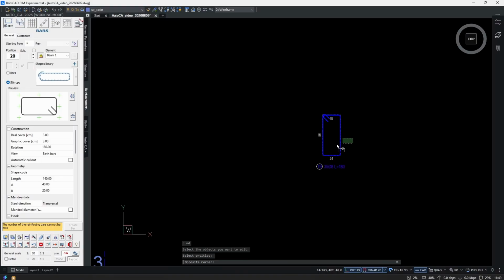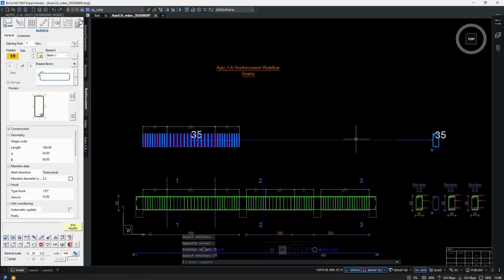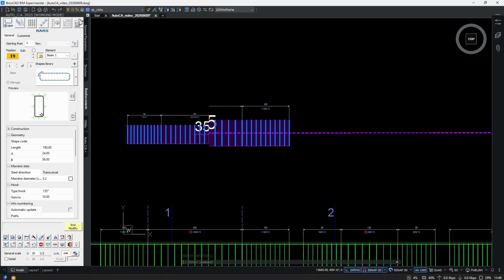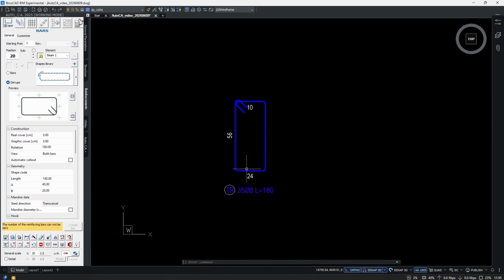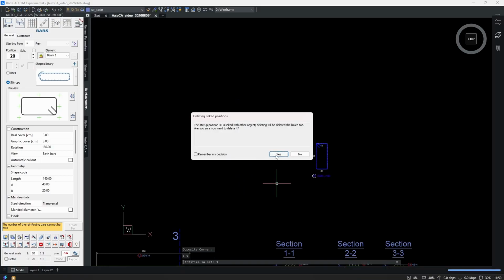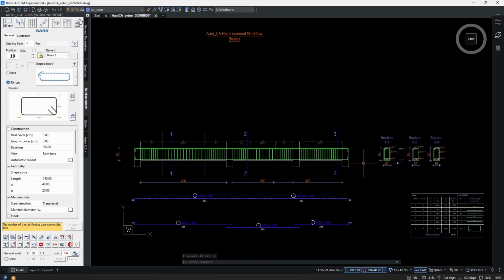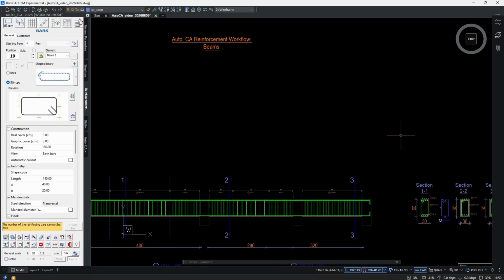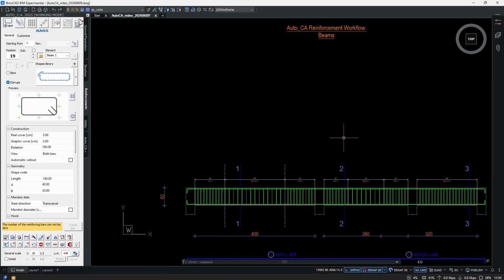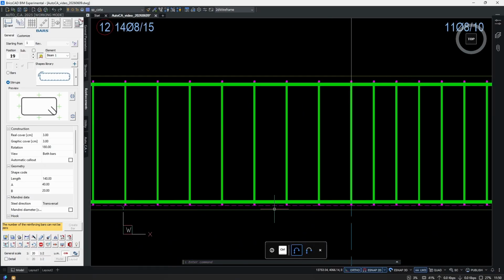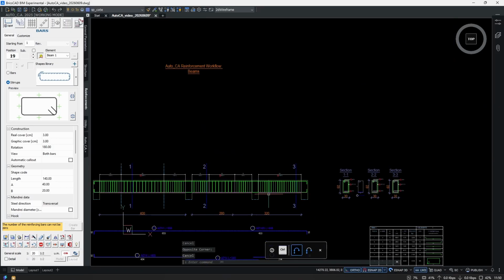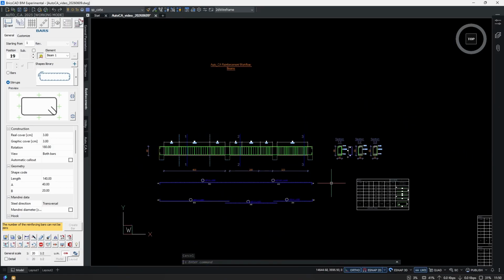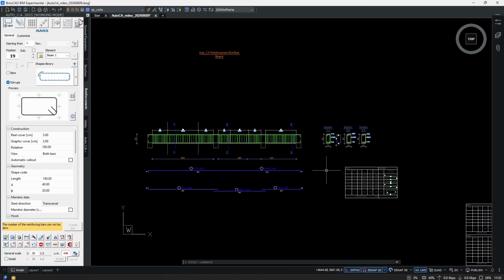It is now a new link between this new distribution and the new outside bar. So it means that the connections are not lost during copying. So you should always keep it in mind. And as you can see, when deleting the outside bar, the linked elements, all the inside bars and the distributions get deleted as well. And let me show you one more thing.